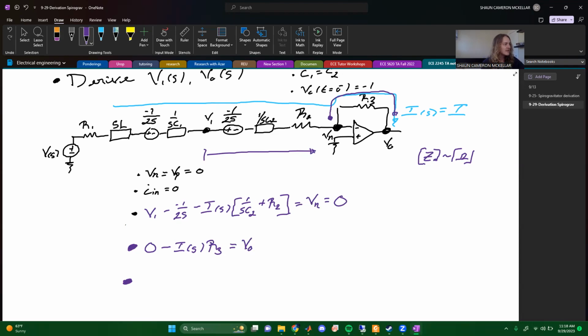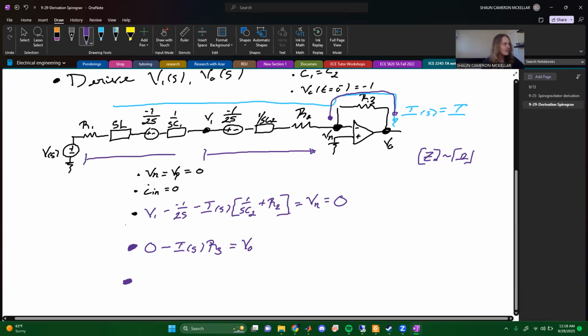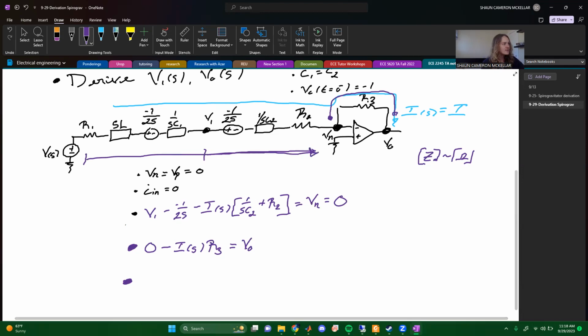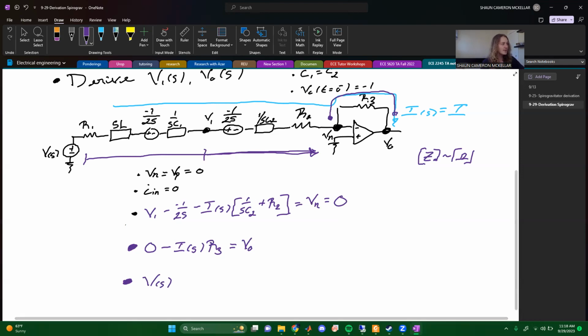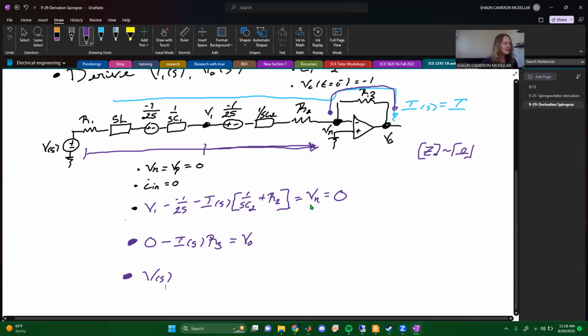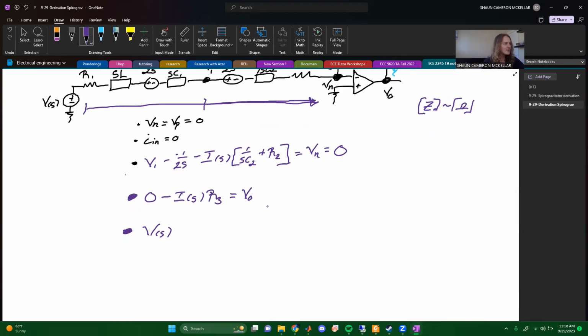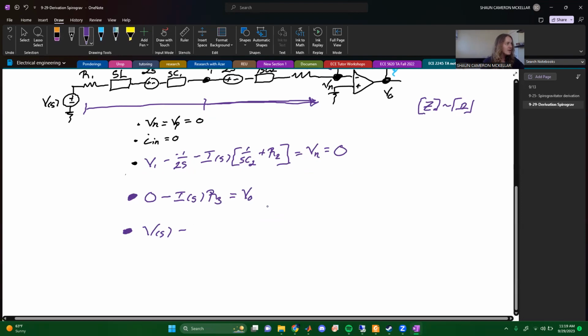Well, let's start at V of S here, and we'll drop all the way down to 0 volts. Okay, so V of S. And then there's a few ways we conceptualize this. We could go through each component one at a time, but I'm going to show you a really speedy way to do this. I'm going to drop the total voltage in this branch.